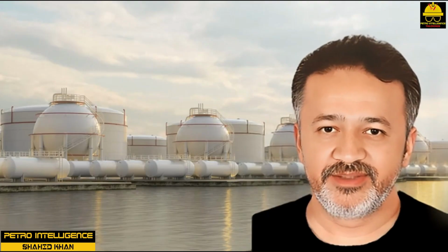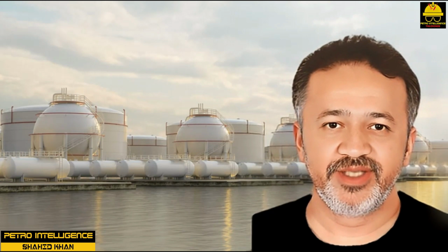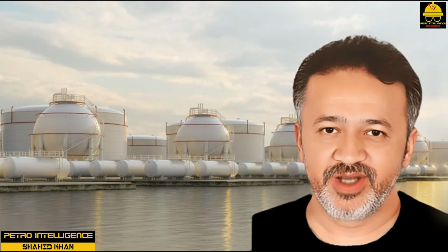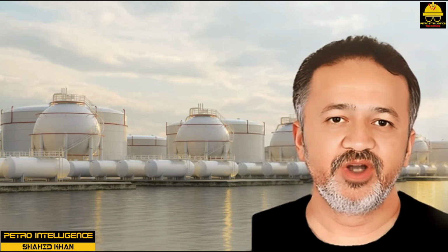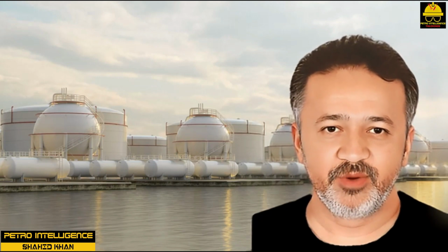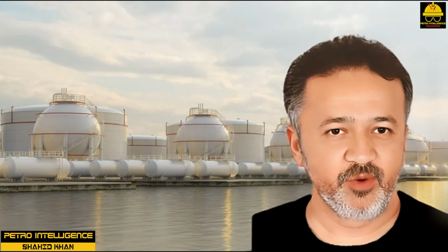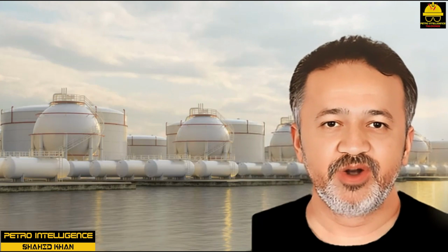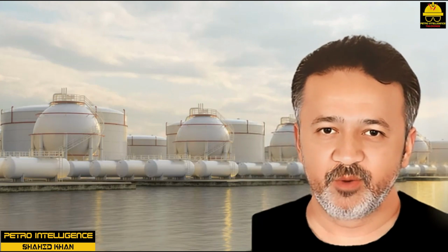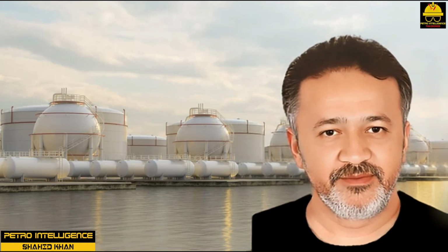Vessel thickness. If the original design thickness of all pressure-retaining parts in a plant could be maintained and the process conditions held constant, the unit would not require periodic inspection and operation could be continuous. Since this is rarely possible, it is important to know what factors affect the initial required thickness of operating equipment and one factor, corrosion, that can reduce the thickness of equipment.